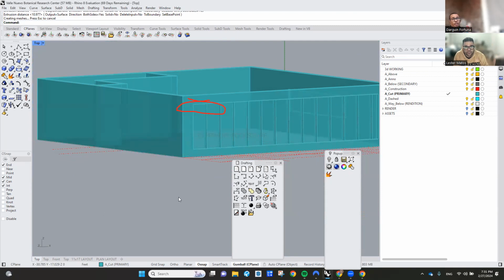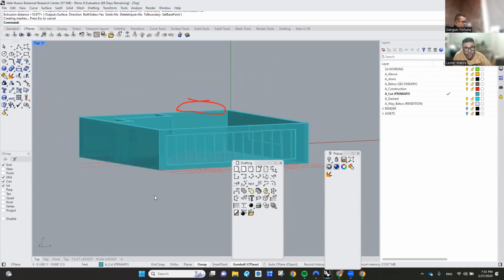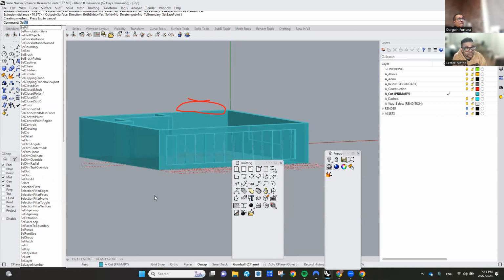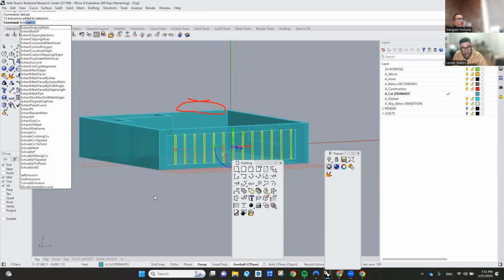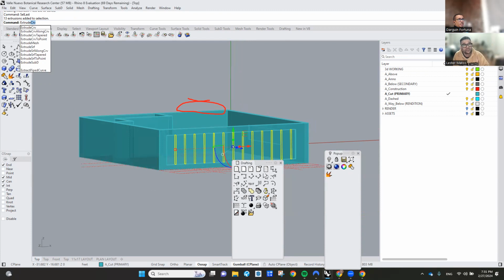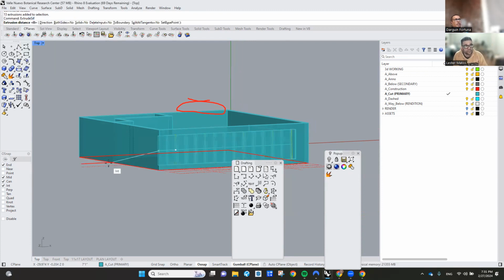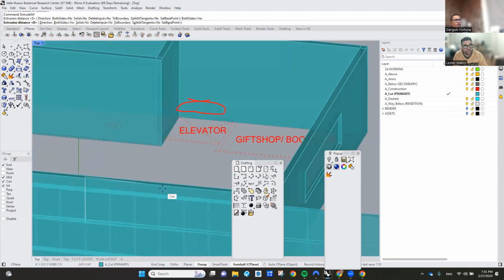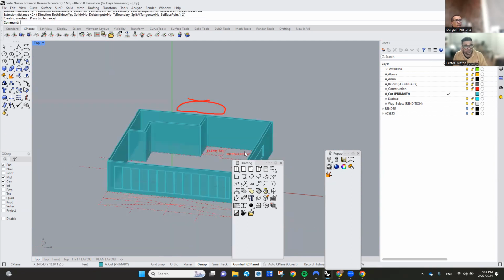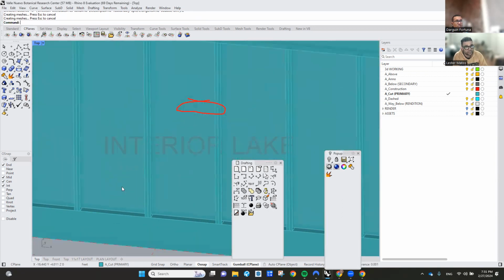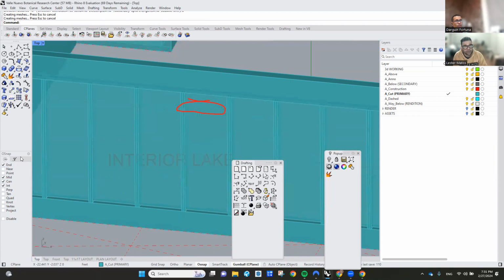But they're like paper thin. So you're like, what the heck? That doesn't have any thickness. Sell last, extrude, but you're not gonna do curve. You're gonna do surface, because those are surfaces. And you're gonna say surface, and then you're gonna say both directions. Now I don't think it's gonna help me much, but you can give it a thickness of, let's say, 2 inches in any direction, so they have 4 inches. Boom. There you go. You got it.